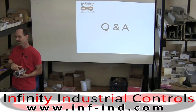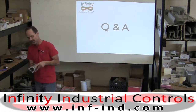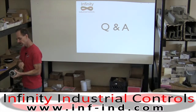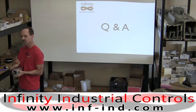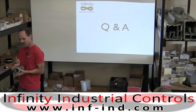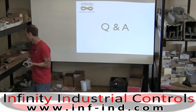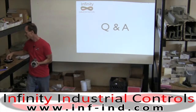As it induces a current, it produces its own magnetic field. So it has an induced magnetic field, and that develops the torque. But the rotating magnetic field actually has to be going a little bit faster than this, because it has to cross these poles to generate. They call that slip, because this is never going as fast as that rotating field.